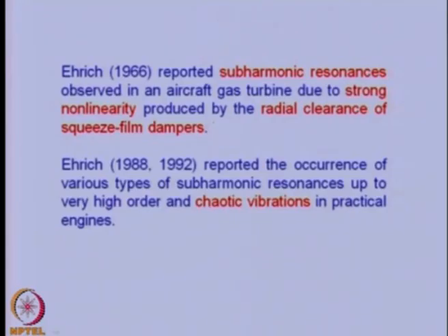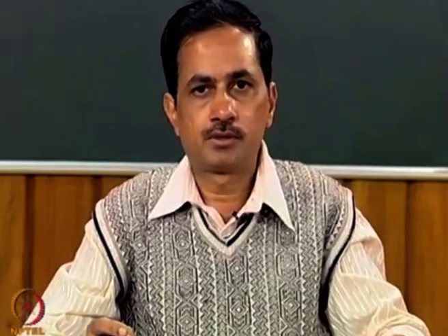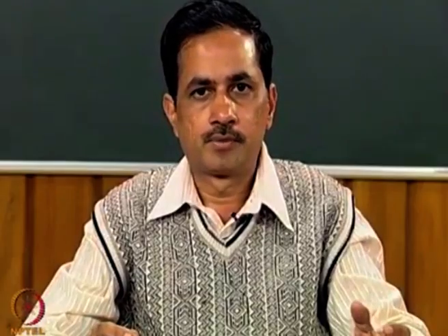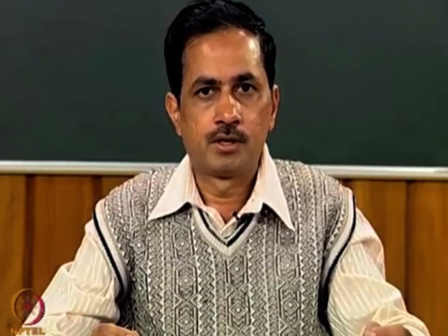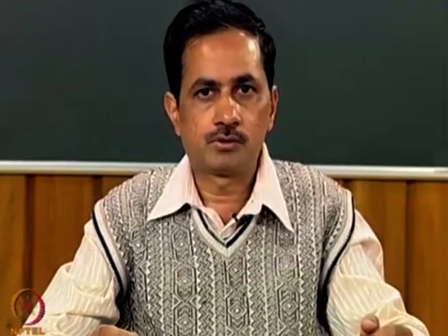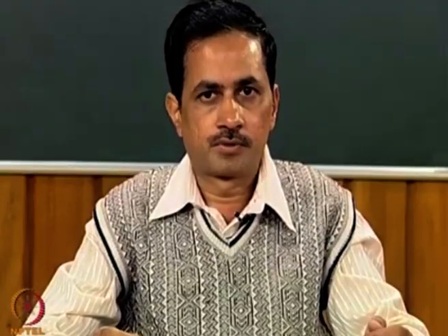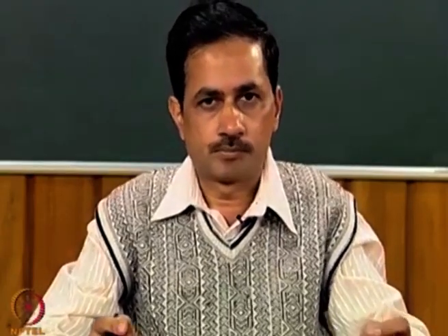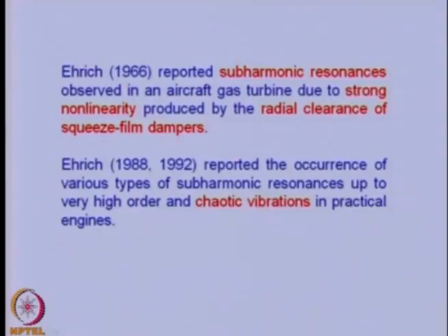These squeeze film dampers are identical to the general bearings. The only thing is that in the squeeze film damper, the stiffness property which a general bearing gives to the rotor is not there, only the damping it produces to the rotor. Then Ehrich in 1988 and 1992 reported the occurrence of various types of subharmonic resonances up to very high order and chaotic vibrations in practical engines.